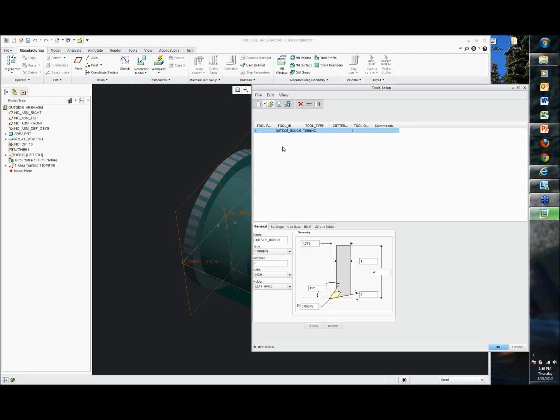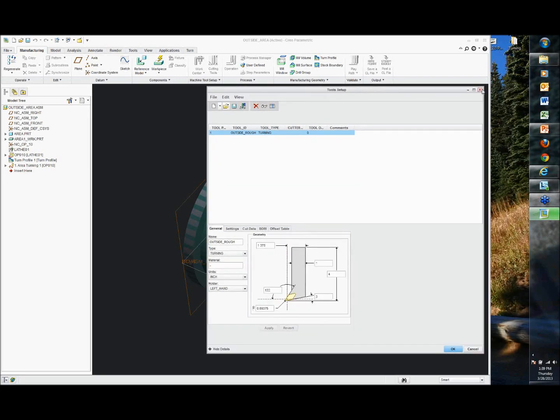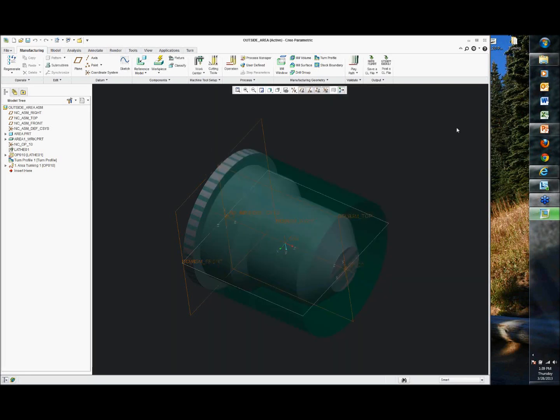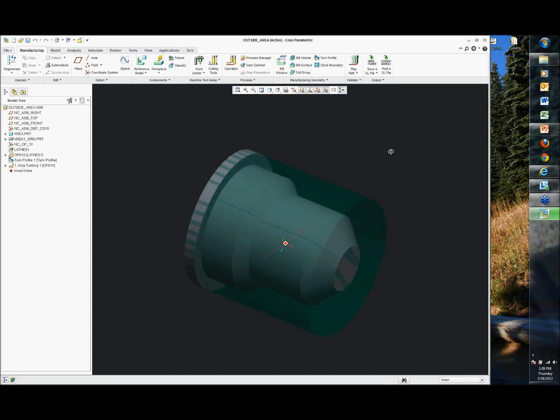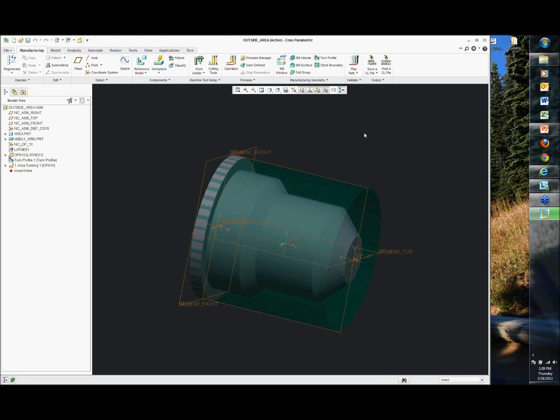Yeah, and my question on the Vericut file was more like, whenever the Vericut creates the material removal. Okay, it doesn't really create it, right? It creates it whenever Vericut's running off of your CL data, it's taking your basic stock and creating what is left off your basic stock from your CL data there. So it creates a file. Yeah, based on your CL file, yes.